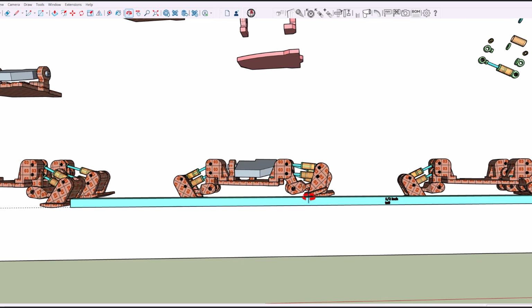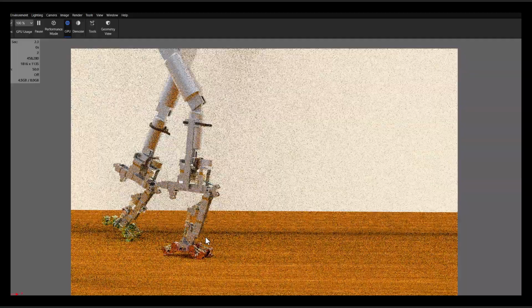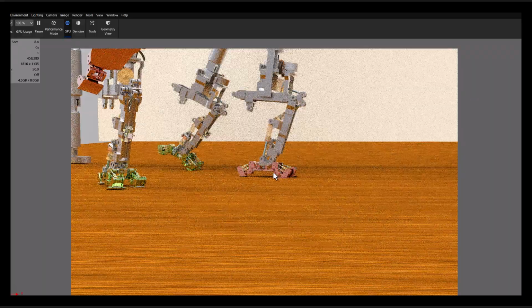And the answer is, if it falls 16 inches under the acceleration of gravity, it will be going at 9.2 feet per second at 16 inches. And so it's going to go from 9.2 feet per second to 0 feet per second over a distance of a 1/2 inch.